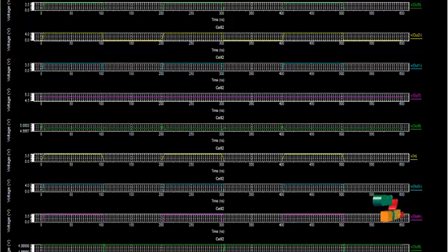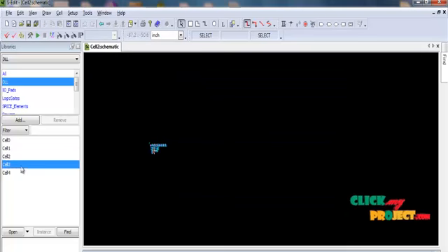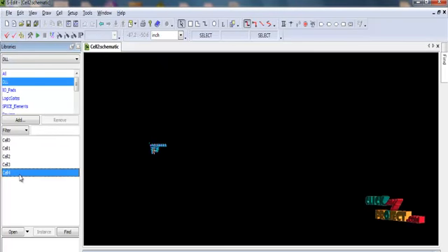These are the outputs of the multiplication ratio control logic. They differ by positive and negative output. The negative output is denoted by the minus symbol, and the positive output is denoted by the positive symbol. This positive and negative edge trigger output will be overlapped. This overlap will be cancelled by using the next cell. Cell 3 is the overlap cancellation, and cell 4 is the final buffer output.